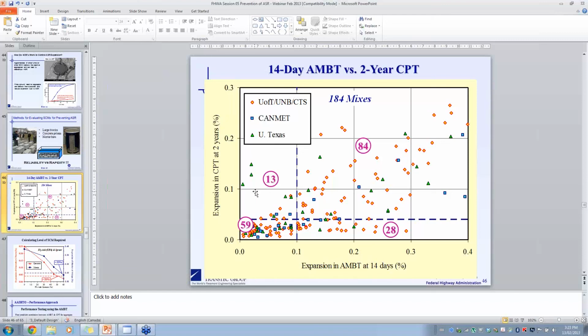You definitely change the nature and the chemistry of the calcium silicate hydrates that form, and so they're the binding minerals, if you like, the cement phases. You change the chemistry of those phases, and that can impact the binding capacity of those phases. But I think essentially you're not so much changing the chemistry of the gel, you're changing the chemistry of the pore solution, which prevents the formation of the gel.